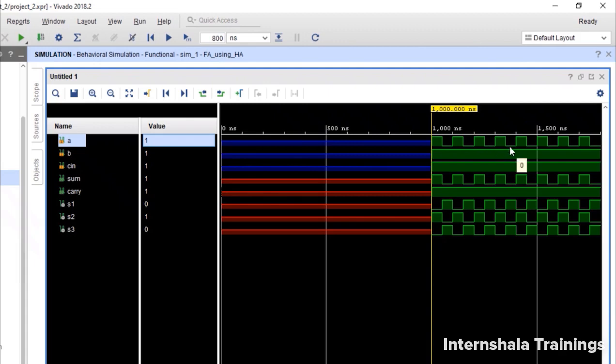So now you are getting an idea that when we write the truth table, the least significant bit is 101010. The next one is 0011 0011 0011, and the next one is 4 times 0, 4 times 1, 4 times 0, 4 times 1, and the next higher one will be 8 times 0, 8 times 1.